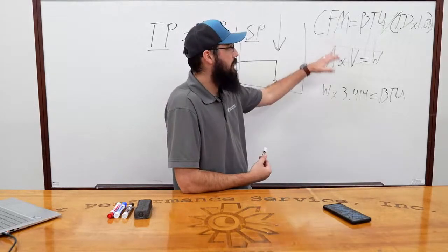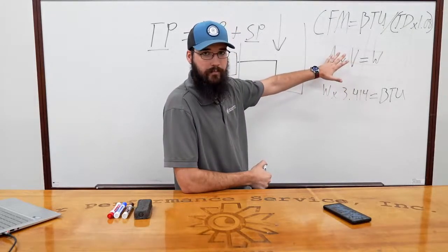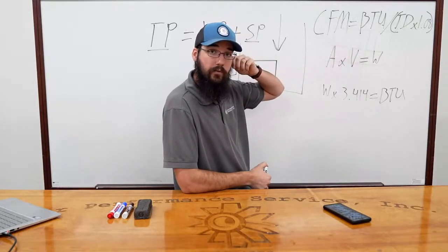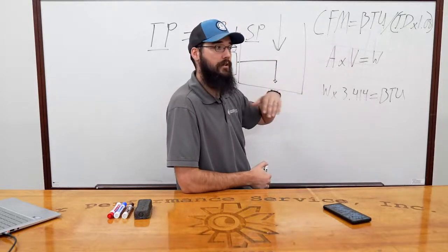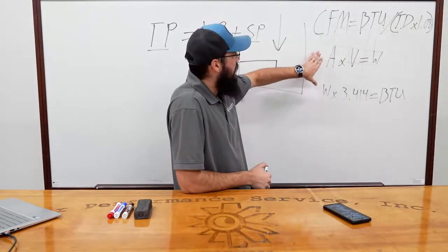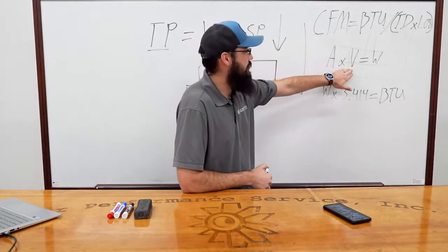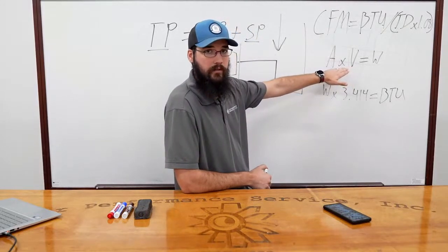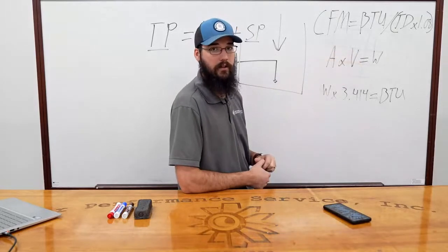Because if you're going this deep, if you need to get this number for whatever reason, maybe you're commissioning. So that would be a real justification for trying to get this number. I need to commission this system or verify commission, whatever. Then you want to take the voltage reading while the heat is going. So take them both simultaneously and plug that into your calculation.